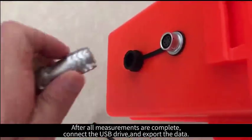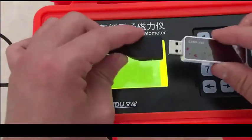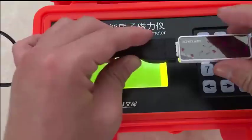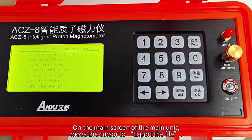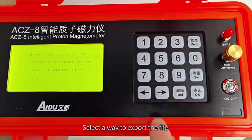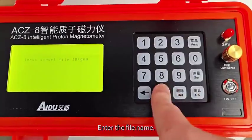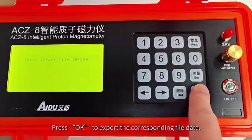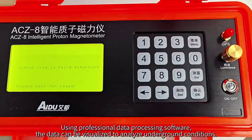After all measurements are complete, connect the USB drive and export the data. On the main screen of the main unit, move the cursor to export the file. Press OK. Select a way to export the file. Enter the file name. Press OK to export the corresponding file data. Using professional data processing software, the data can be visualized to analyze underground conditions.